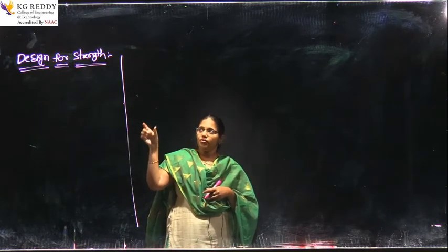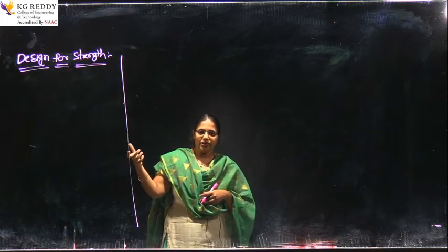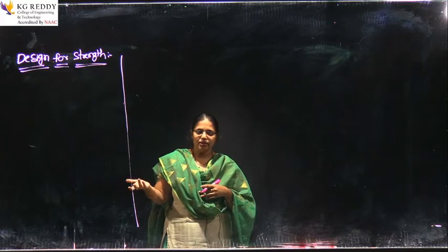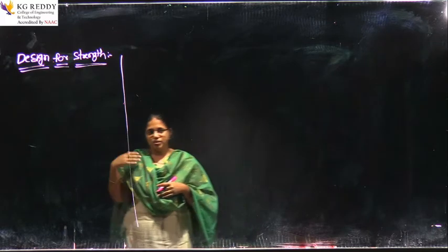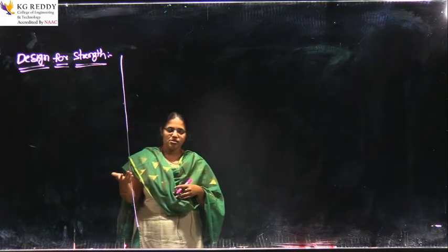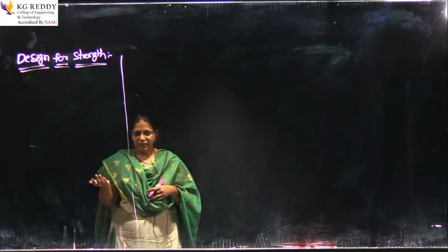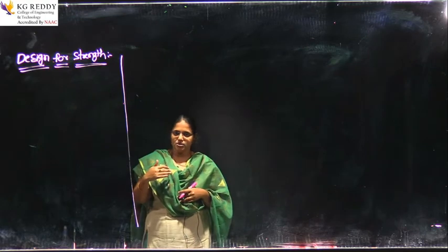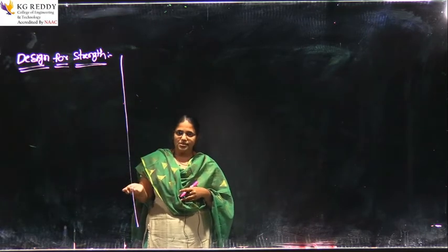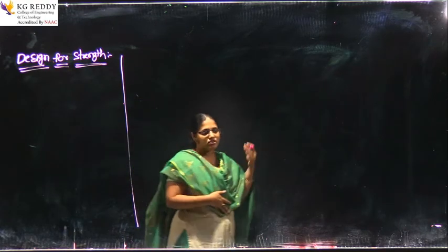So, here I want to know the strength of the material. How can I know that strength of the material? Based upon conducting experiments. So, what type of experiments I need to conduct? I need to conduct them based upon the universal testing machine. Okay. So, tensile test, compressive test and also shear test.